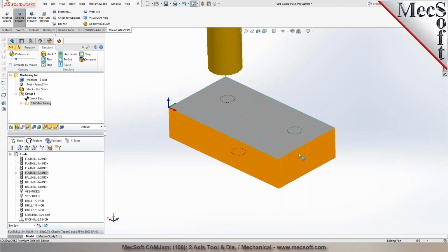Okay, so you would either have to extend the stock, basically have it go past it. Right now it's stepping over to the extent of the stock. Or if you choose to do a climb cut, then it'll be cutting in one direction, and you can do an entry and exit to extend past it. So if you wanted to extend past by a certain amount, you can define a sketch to overshoot it by that amount. Okay.